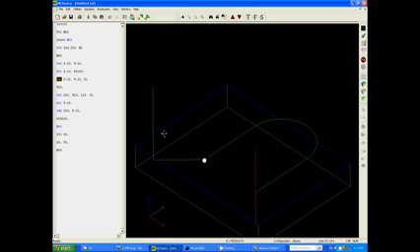We want to machine the outside, so we'll use left hand radius compensation and move it to the side of the job. While we're doing that, we're going to call up the radius offset number 1. Now it says D1, but it will actually call up the radius.